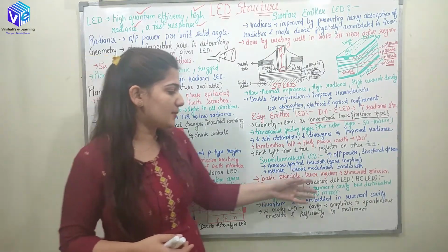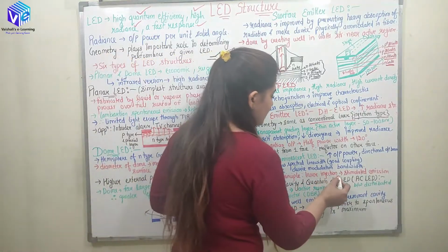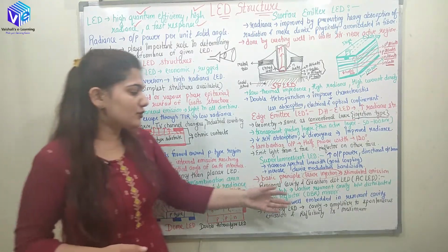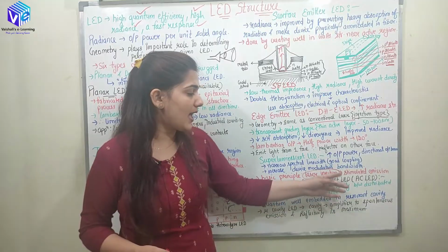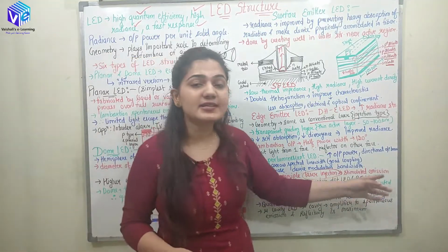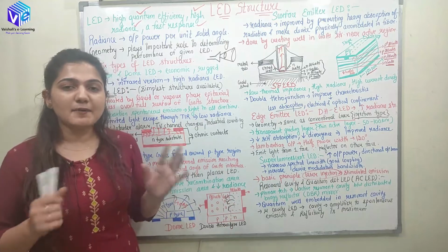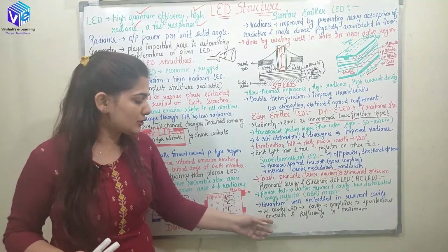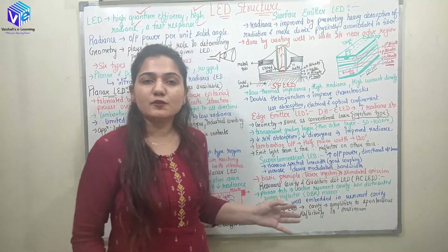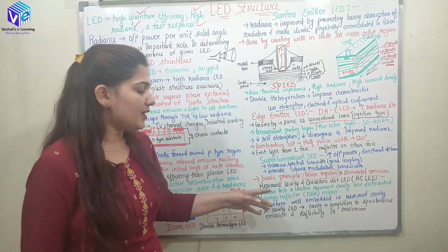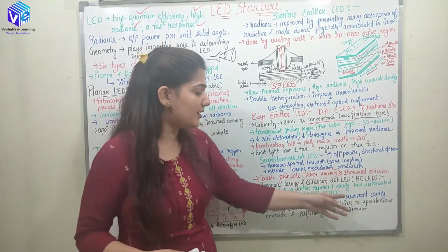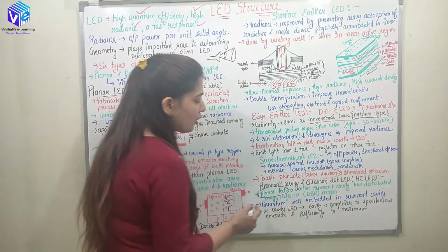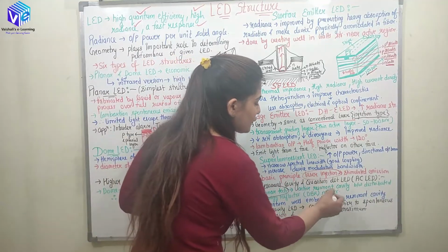So now coming to the basic principle, I told you it is working upon the laser injection principle, which is the stimulated emission. Now coming to the resonant cavity and the quantum dot LED. It is also called RC LED. It is again a very important type of LED which is used in the advanced applications where again the cost is not an issue. It is also called micro cavity LED, or mu cavity LED. So here we will be having a quantum well which is embedded inside the resonant cavity, and it will be having a planar structure. Okay, so the planar technology will be used to make the active resonant cavity.